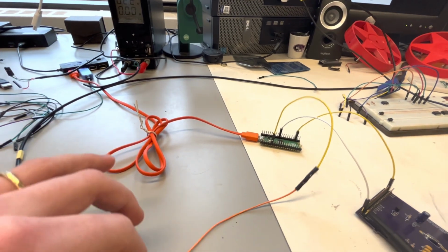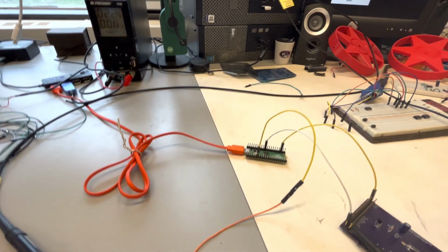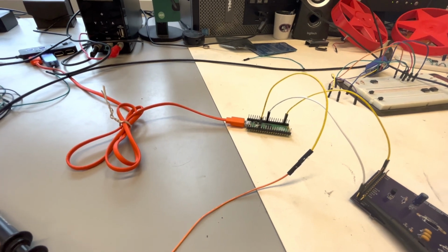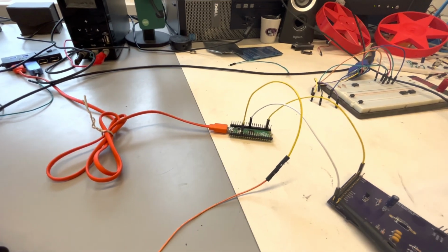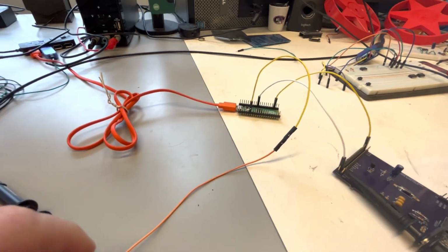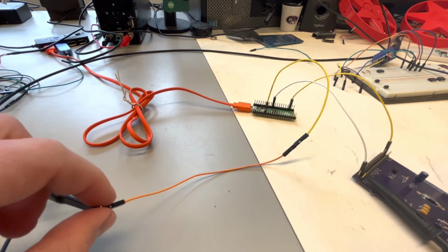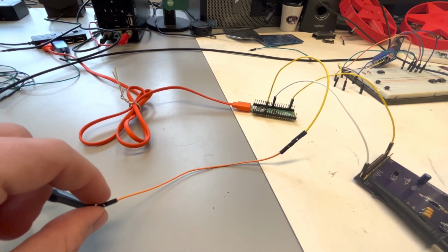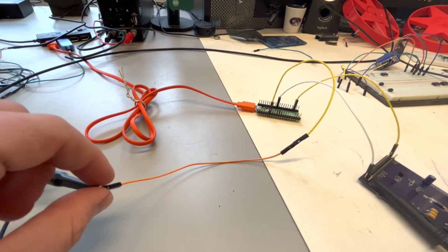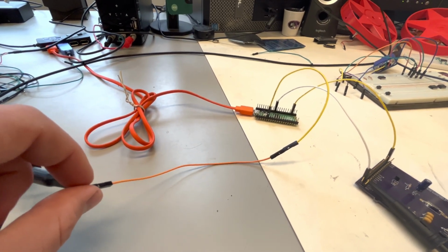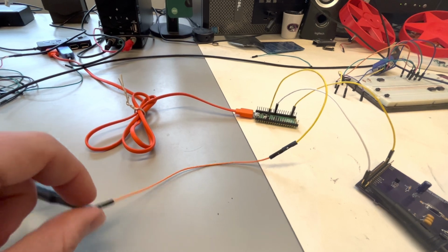The PWM channel that we'll be driving into this jumper has a clock divider of 1 and a wrap value of 255, and I've overclocked the RP2040 to run at 250 megahertz. So that means the frequency of this PWM signal will be right about 980 kilohertz. So that's going to be the frequency of our carrier wave. So when we tune our AM radio to hear these transmissions, we'll tune it to 980 kilohertz.